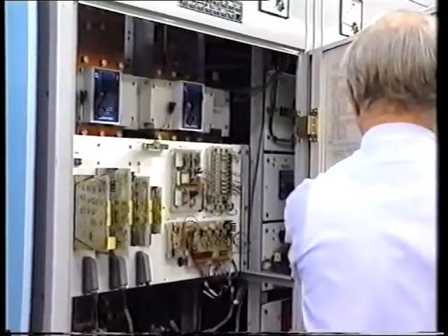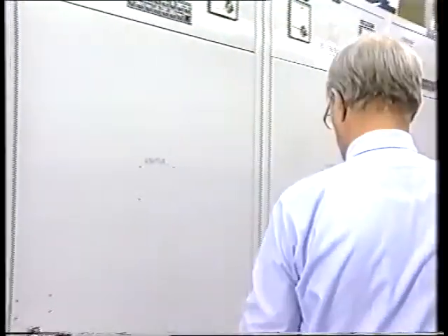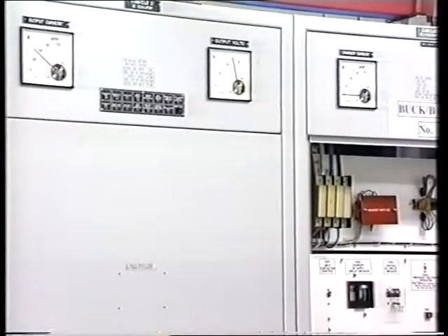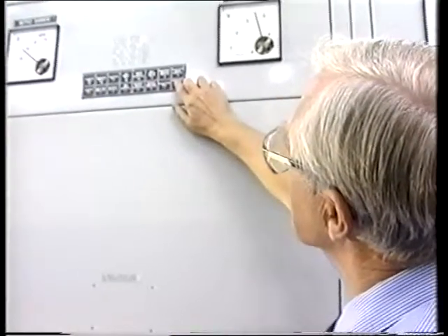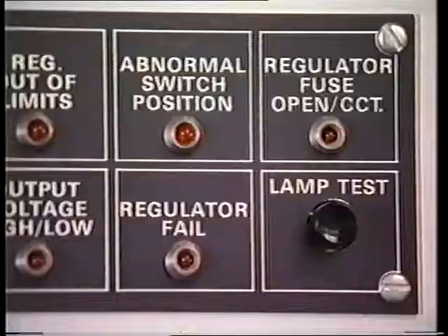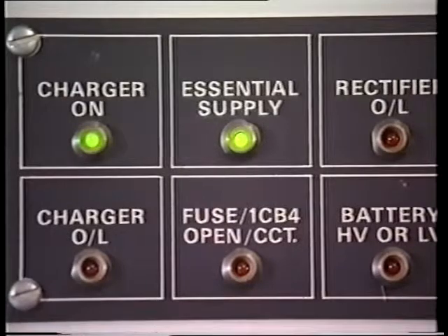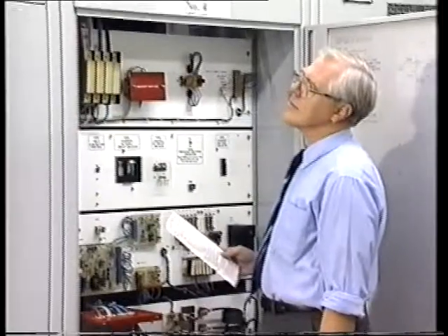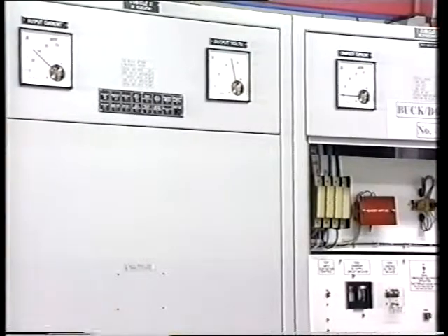For a variety of reasons, local operational staff are required from time to time to operate this plant. Extreme care should be exercised at all times to prevent misoperation, which could place the network at risk. Each buck-boost power supply has a comprehensive alarm display located at the top of each cubicle. For normal operation, 4 green indicators should be on. A red or orange indicator will show any abnormal conditions with the plant. Careful diagnosis of alarm indicators should be done before any operational procedure is attempted.